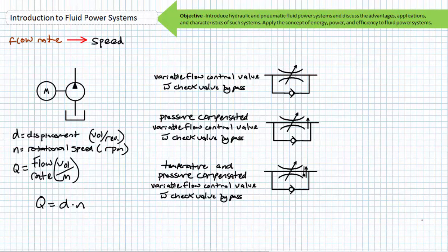Flow control valves ordinarily feature a restricted orifice that can be varied opened or closed as conditions dictate. Flow rate is measured using a flow meter, symbolized by a baseball-looking thing. Flow meters are ordinarily direction and gravity dependent, meaning that flow to be measured must come in the in door and out the out door if the flow meter is to return accurate data.